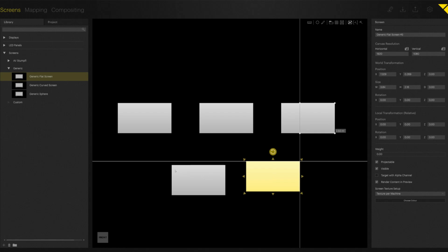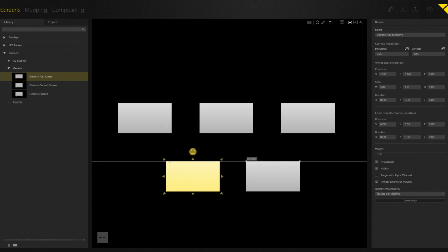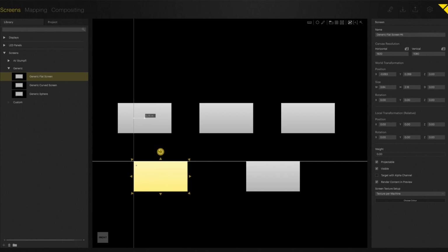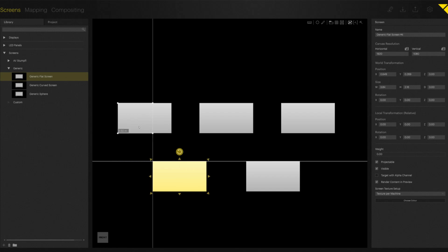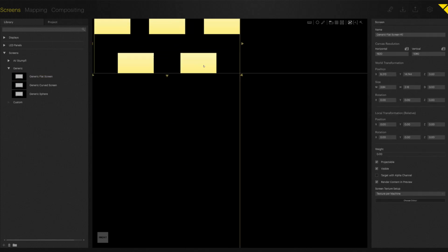And it's the same for the last screen, so I select it on top because I'd like to have it in the same level up here, and then I select it again, press Shift. You don't have to keep Shift pressed, just click on it or press on it one time, and then you get the reference line here again, and I just move it to the very left border of the top screen to get the reference here. I just click in there and type in 2.5 again. So now I have my first arrangement of the first 5 screens. I also can select them all, move them somewhere else.